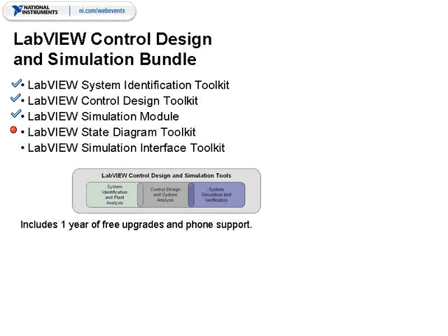specifically the LabVIEW State Diagram Toolkit, which allows you to represent state machine logic directly in a state diagram form and eases the creation of state machine logic and can be used together with the simulation module for modeling hybrid systems and developing hybrid control systems. In addition, this bundling also includes the LabVIEW Simulation Interface Toolkit, which enables you to use Simulink models further, specifically by using LabVIEW as a user interface directly for the Simulink environment for offline simulation or real-time implementation on LabVIEW real-time hardware targets.